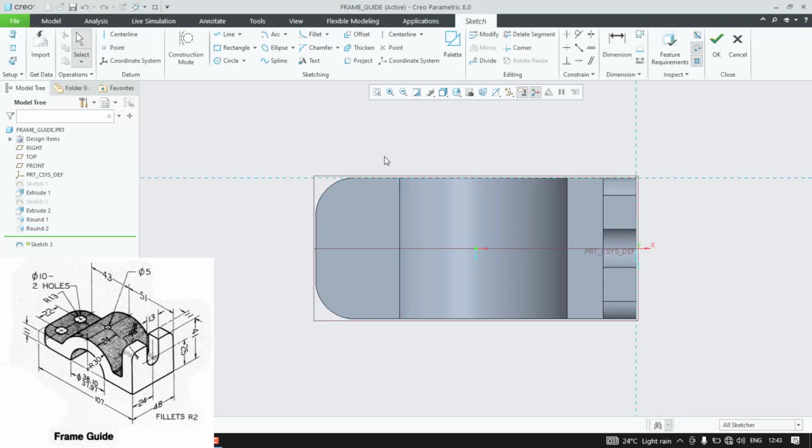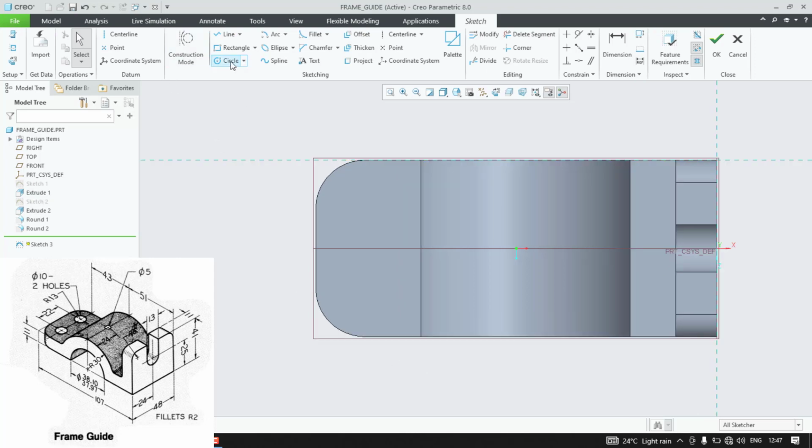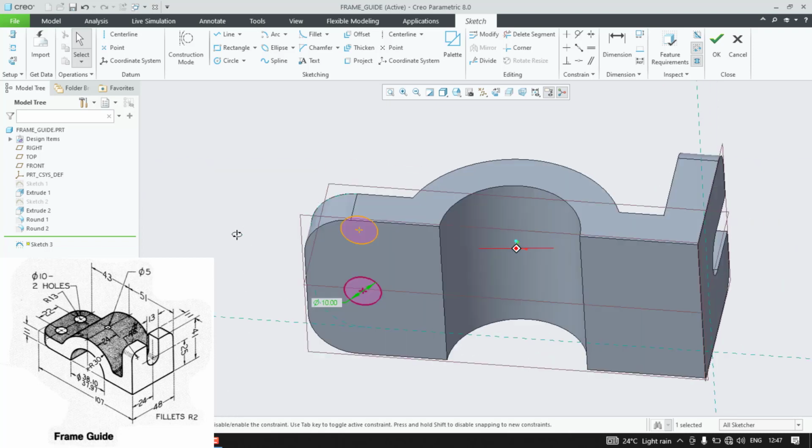So I want to snap the center of the arc, so that I can select the circle and just hover on the arc. Okay, you'll get the snap point, create the circle there. So you could see once you just get the equal symbol, it will try to snap the diameters. Okay, if you change one side, it will change the other side because it has the equal symbol.